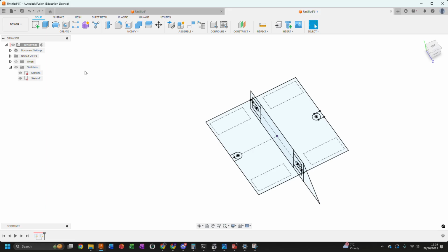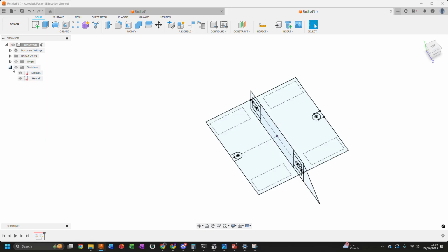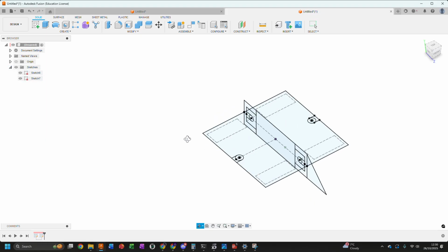One thing I have been doing but haven't really been talking about is you can hide sketches and make them visible, basically, as you wish. So if we want to look at our sketches, we hit this arrow here, and we select the eye icon, toggle it basically to view and hide our sketch. So there we are. Sometimes we want to hide sketches to see our bodies without all the messy geometry that we used to define them. So that's why that's an option.